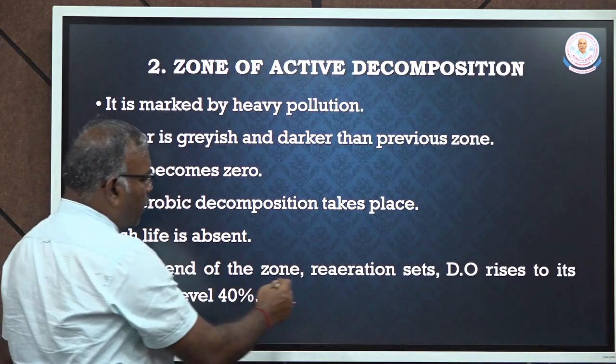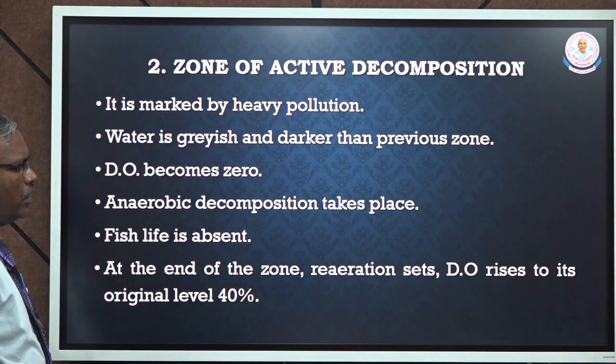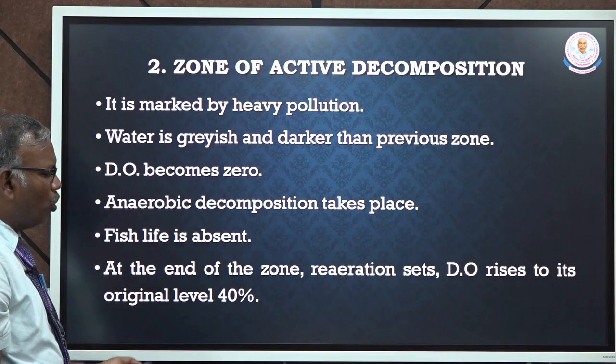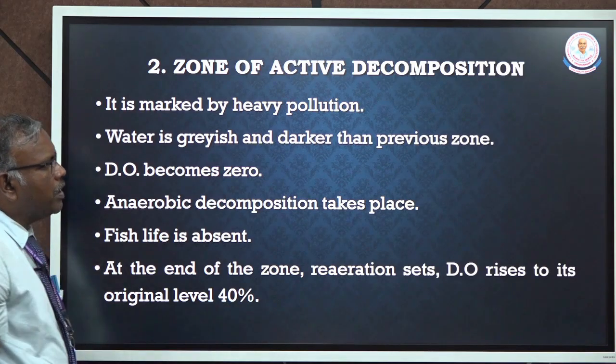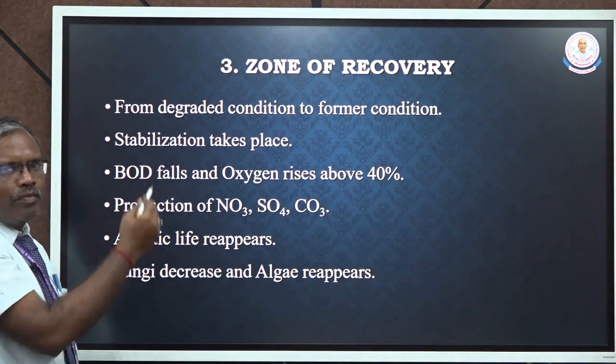Next, after this point, the re-aeration takes place, and there will be an increase in the DO level up to 40% in this decomposition zone. Next, recovery.